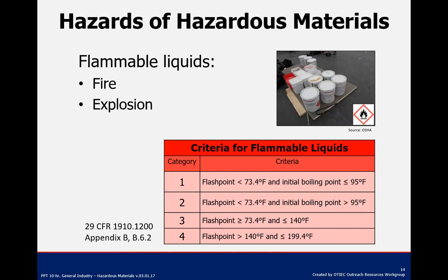So flammable liquids mean liquid having a flash point of no more than 199.4 degrees Fahrenheit. Flash point means the minimum temperature at which a liquid gives off vapor in sufficient concentration to form an ignitable mixture with air near the surface of the liquid.